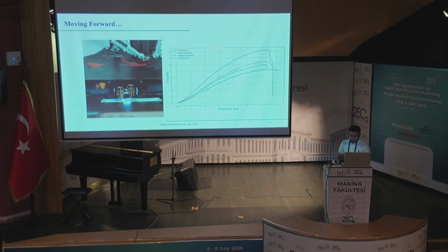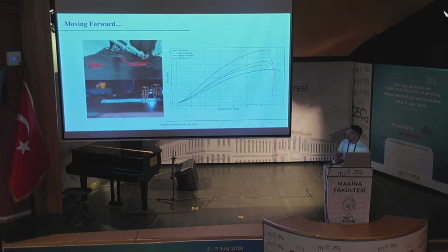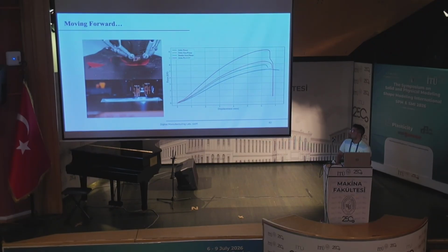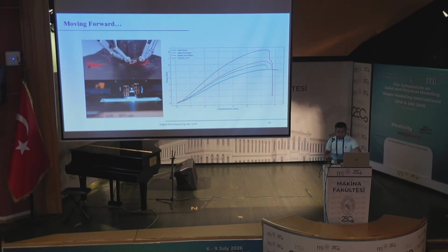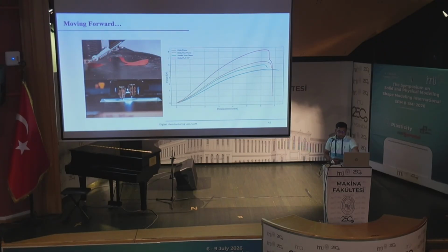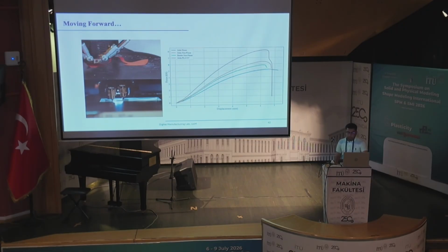Moving a step forward, some of the applications that we showed here used robots or a little bit expensive devices, but then we tried it on commercial, cheap printers. On the top we saw a Delta printer, and at the bottom the quite popular Bamboo printer. Despite having very little clearance and only slight three axis motion for those printers, on the graph we can see that compared to planar printing, it still leads to significant improvement, and there is huge potential if the manufacturers start providing a bit more clearance, and hopefully they will in the future.